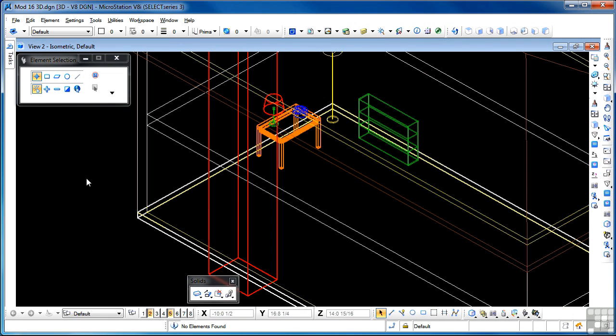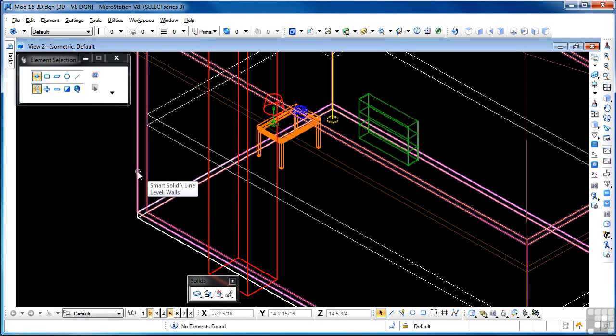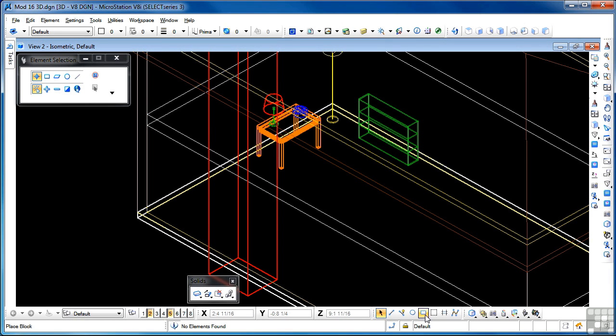And we'll zoom into here. So my window needs to go in here. And again, the details for the window are in the House Renovations file. And it's a 4-foot square window, 1200 millimeters. And as I said, just a little bit to the left of the chimney, and with the base of the window approximately 3 foot above the floor level. So let's start that process right now.